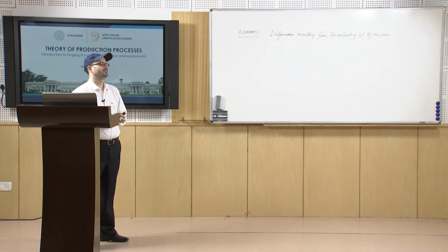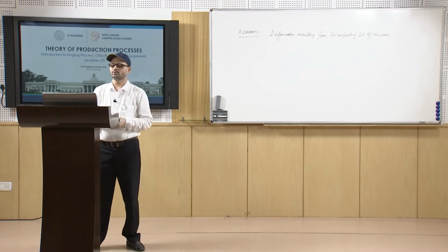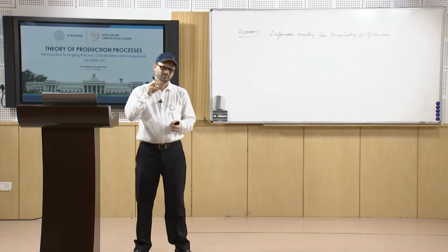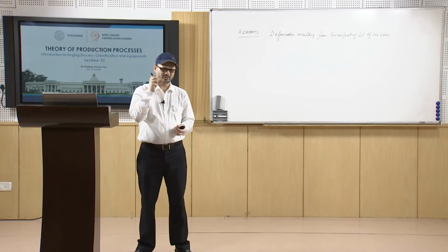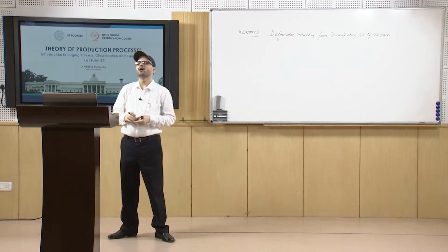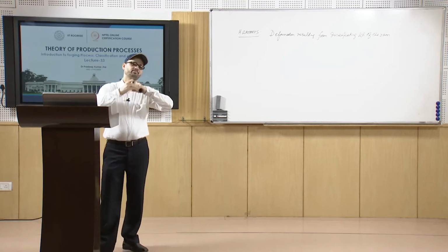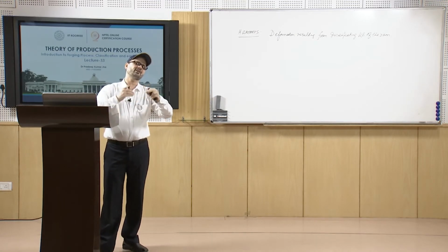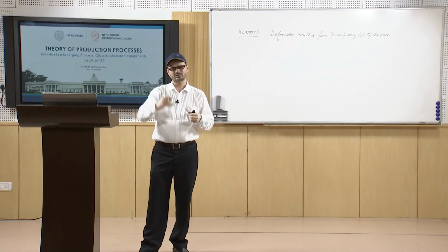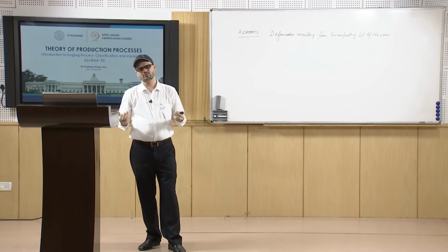Since it is giving extra power, it is known as a power hammer. You have basically two kinds of energy. One is due to the pressure applied on the ram because of the air or steam pressure, that is P A into H. The other is half m v squared, the velocity with which it is falling, and that energy will be converted to m g h or so.